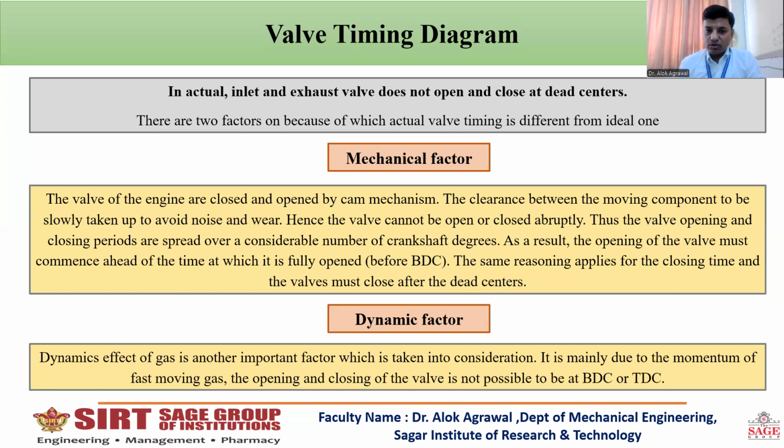So if we close the valve suddenly at dead center, that inertia will tend to hit the inlet valve in case of the suction stroke, and in case of the exhaust stroke, it will tend to hit the exhaust valve, and this will damage our valve.